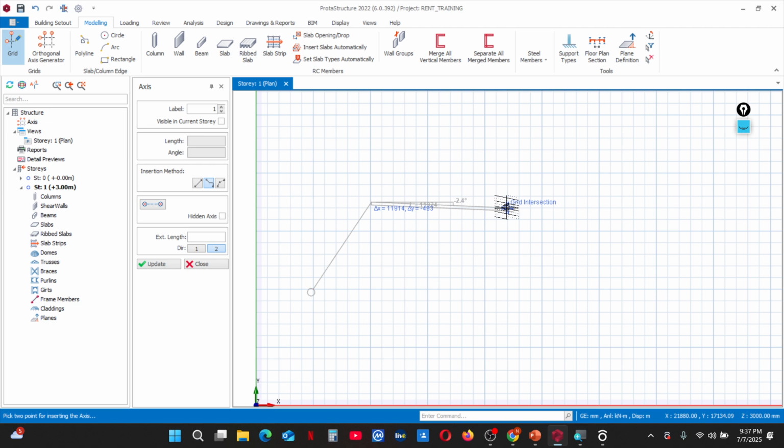Alternatively, you can also press Shift plus F2 on your keyboard to specify a particular distance, just like so. I choose 10 meters. Alternatively, you can also use your control key to align it the way you would want. And then finally, you can come down anywhere, maybe here, continue like that, and then you can come down here.